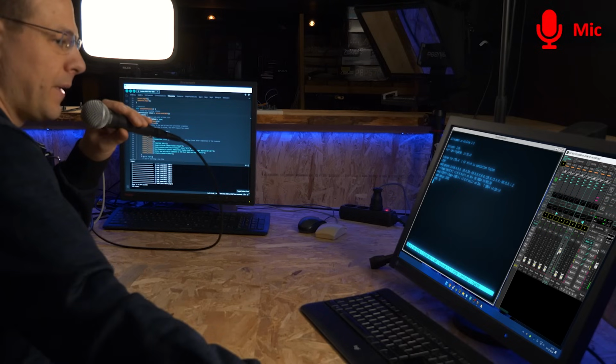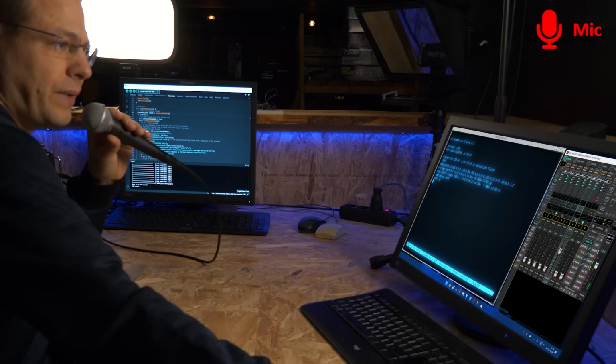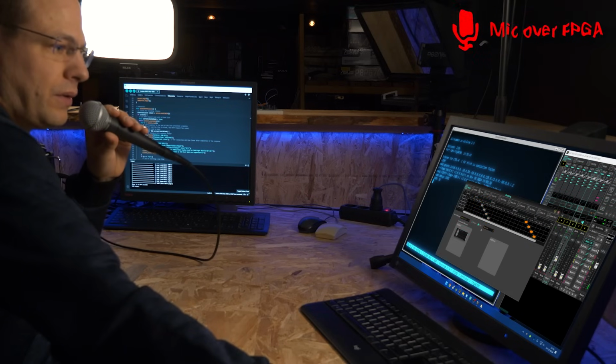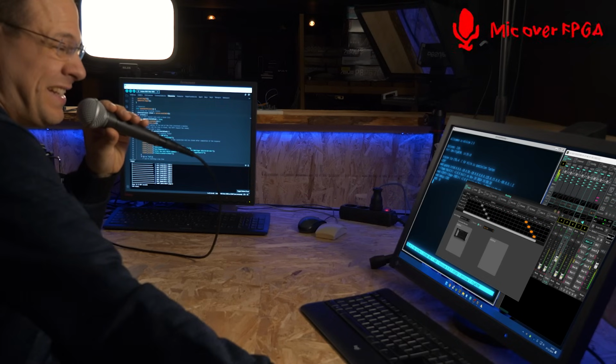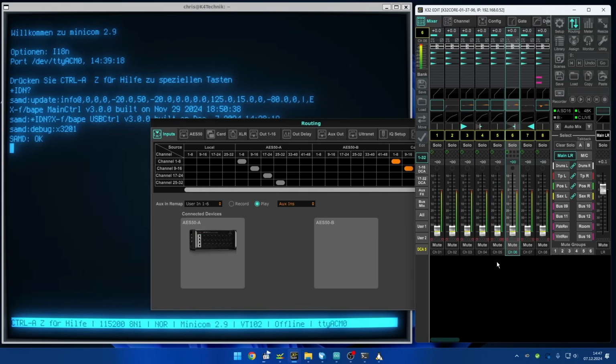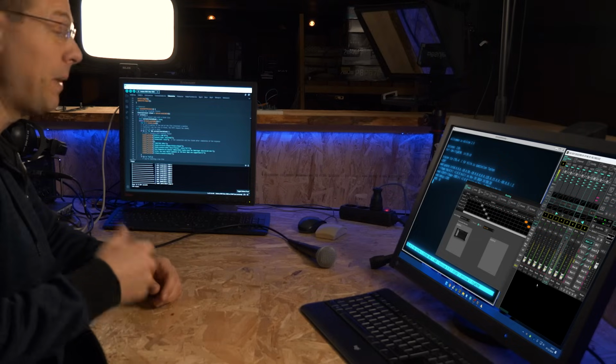So first let's try the general processing. Okay, now you should hear me through the microphone, so that's still working, that's great. And now I'm changing the routing and getting down with the voltage a bit. Okay, this seems not to work. As you can see here in the X32 edit, all signals of all 8 channels are at 0 dBFS, so we have a lot of disturbances here. Maybe a bit shift in the signal we are receiving, I don't know, maybe the transmitter.